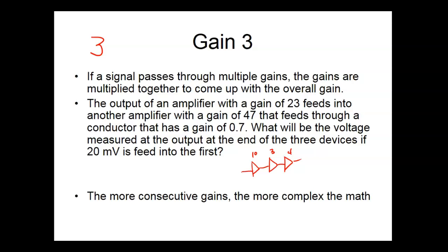So this is what we can do. We start off, and this is why amplifiers have multiple stages. First of all, we're trying to get impedance matching. And the more gain you have, the noisier the amplifier is, because it'll pick up all kinds of stuff. So we start off with low gain, and then we move toward the output, right? Does that make sense?